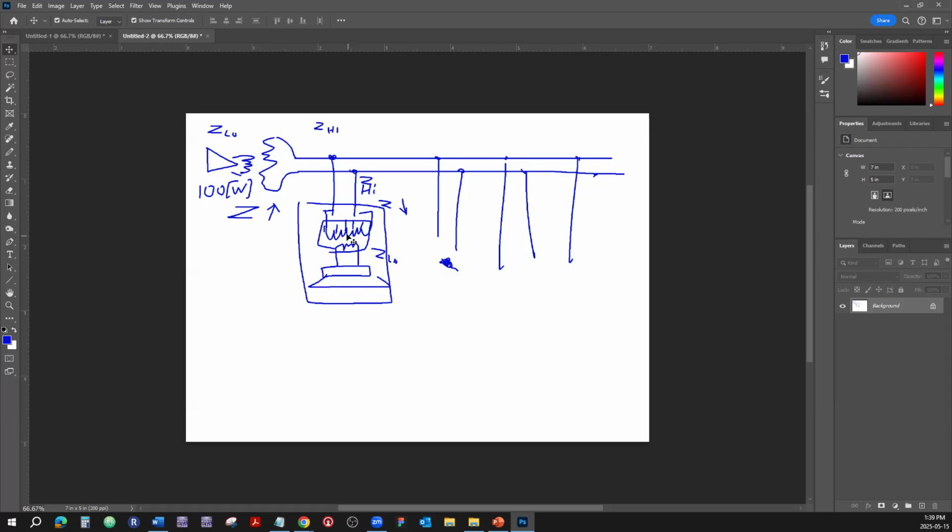And the transformers will have a sticker on one side that will explain to you which color of the wire corresponds to 1 watt in a 70-volt system, and which other color you would have to use for 1 watt in a 25-volt system. We'll show that to you when we are in class. In class, we do have 70-volt systems, so we're going to use that 70-volt explanation on the transformer.